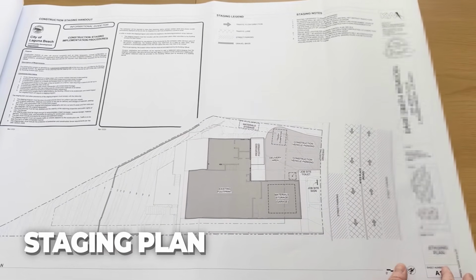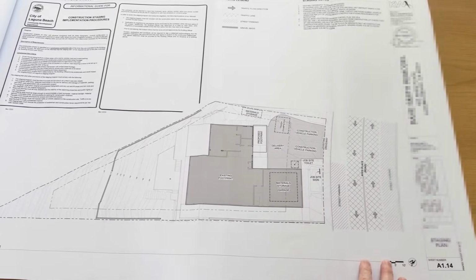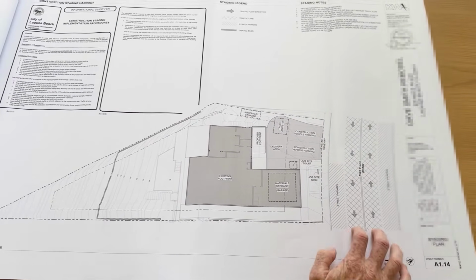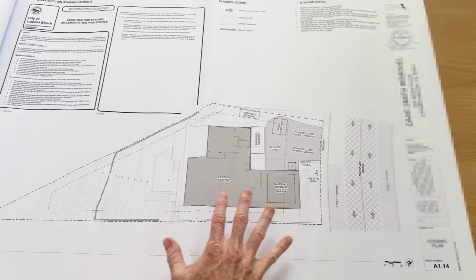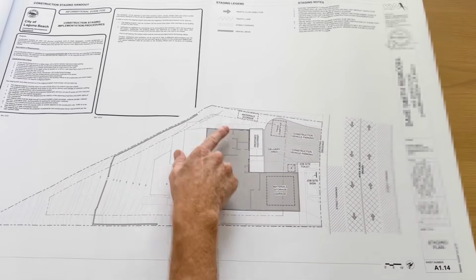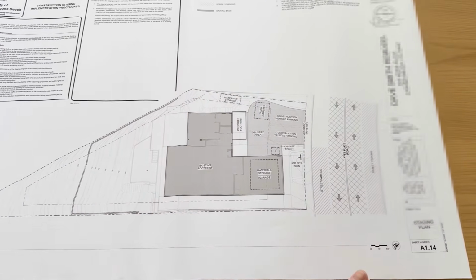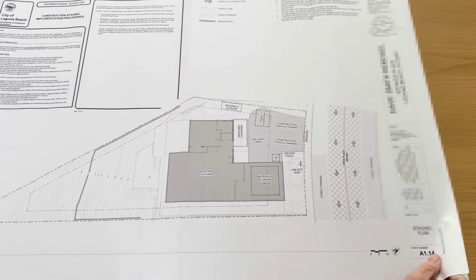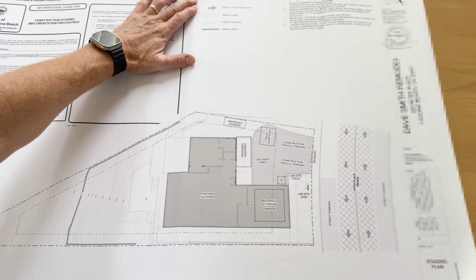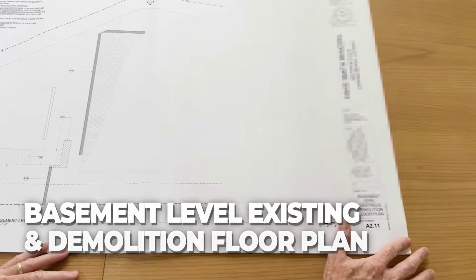Staging plan, this is again, not always in projects, but you've got your main thoroughfare as far as road here, road access. This is basically talking about where during the build process we're allowed to store materials, okay? So it's indicating that we can store stuff here. We want to make sure that there's a trash dumpster. We want to follow all these rules that have been approved by the county or the city. So, okay, and again, if in doubt or when there's questions about what something means, just look for your legends, okay? Basement level existing demolition.